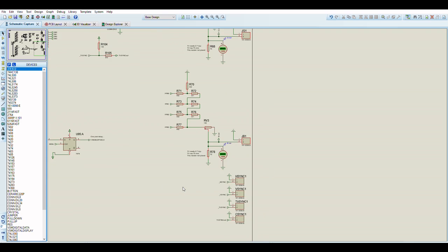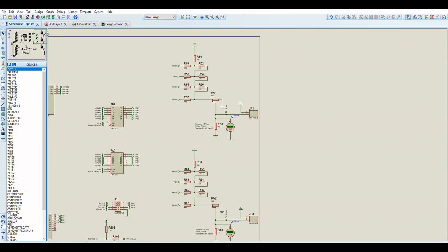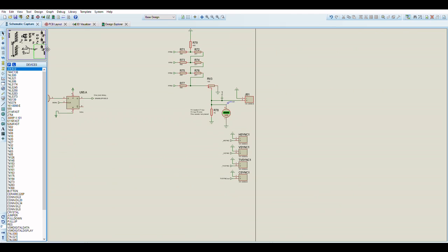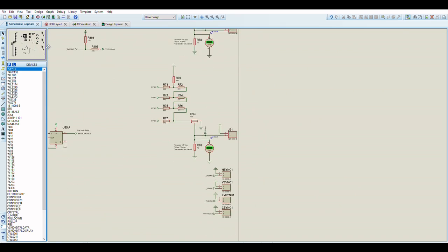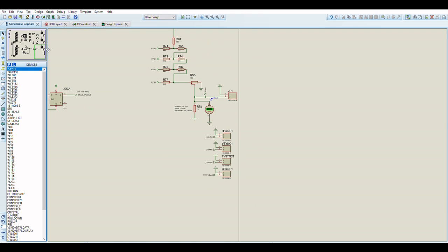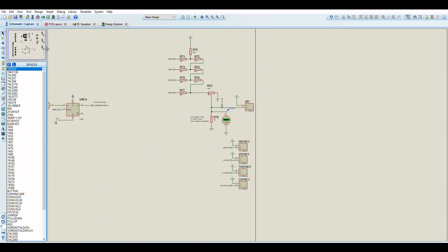So I just left it all digital, and I validate these by checking the voltage results. And these resistor ladder arrangements do not change. So I just tested it once and then disabled it all for the simulation, but it's still obviously enabled for the PCB layout.